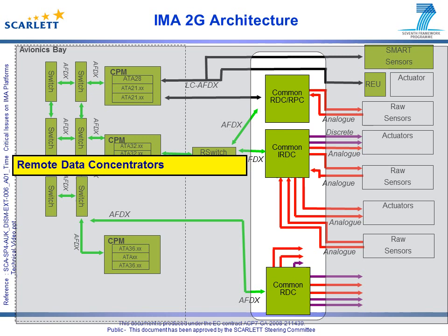RPC, Remote Power Controller. This concept provides higher power outputs for driving loads which cannot be driven from RDC. Above a certain power level, extra protection is required, and this impacts the utilization rate of the I/O on the RDC. IRDC, essentially an RDC with the ability to run 2 or 3 applications.